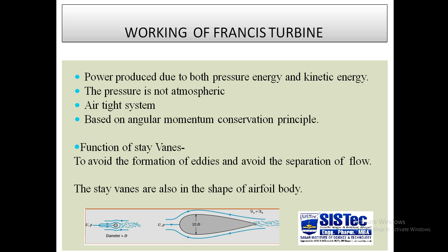A stay vane is also provided at the outer portion. So what is the function of those stay vanes? The function of stay vanes is to avoid the formation of eddies. What are eddies? When anything, any block, is attached with water, and water strikes it very fast, due to turbulence some waves are formed. These waves are called eddies.